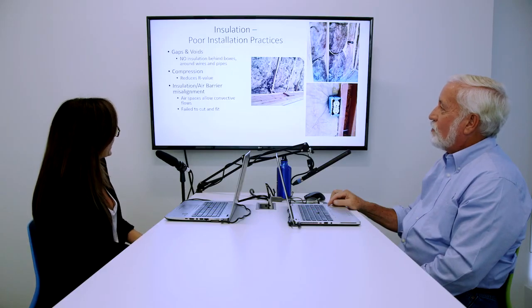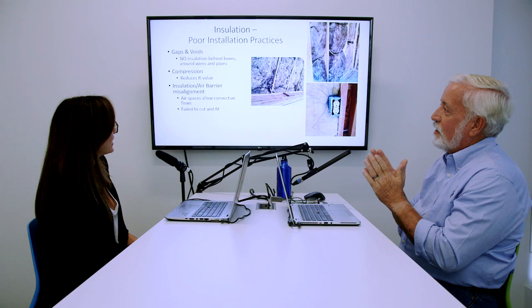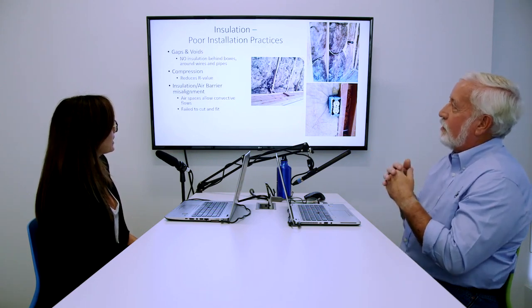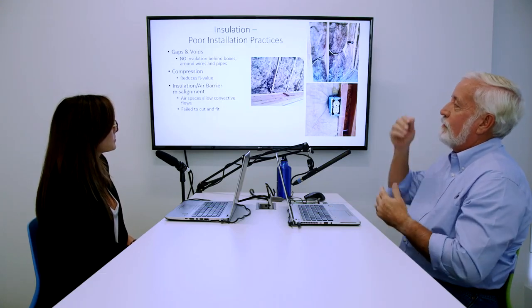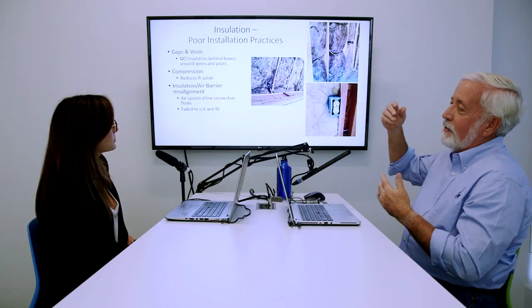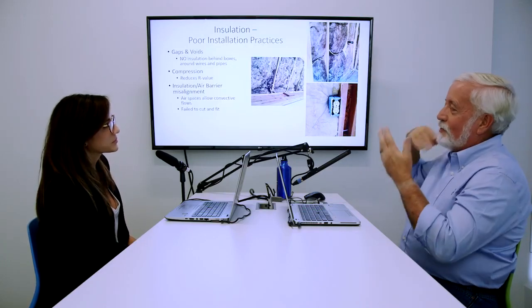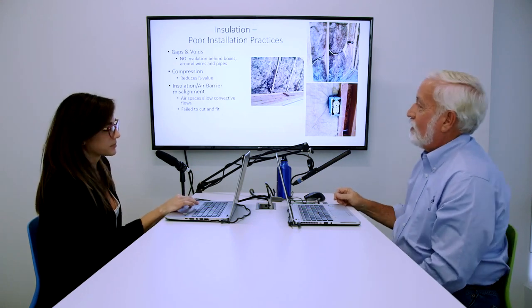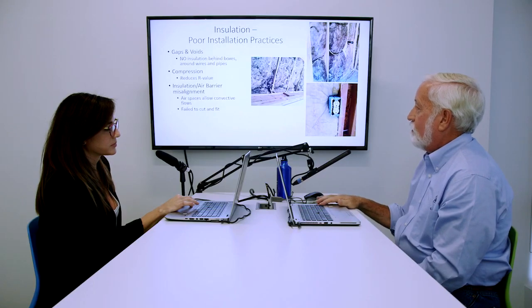And so if we don't have insulation and air barriers aligned, we have those air spaces, and we have those convective flows again with air that can move around in there. Because what's the air going to do? It's either going to see a warm surface or a cold surface, and then it's going to start moving. Why? Because of convection, it rises. And then we just get this circulating air in that cavity, and less R value. And it's simply because they failed to cut and fit it.